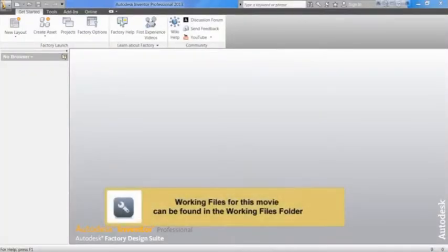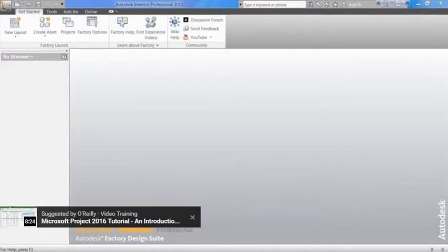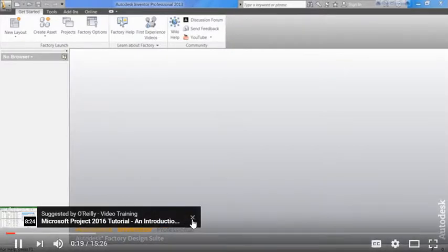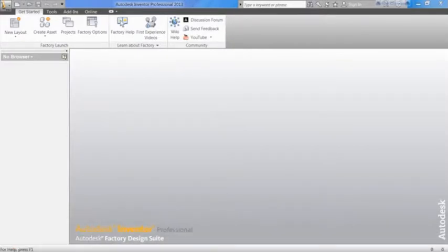In this lesson, we're going to be discussing geometric constraints. There are several different types of geometric constraints, each with a specific capability and purpose. The selection you choose depends largely on the design intent. As you create sketches, some constraints are inferred or applied automatically. In most cases, inferred constraints are sufficient for your initial constraints. As you continue to develop the sketch, you may need to add additional constraints to properly stabilize the sketch geometry.